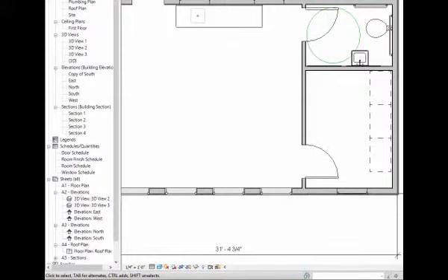As you keep on going with your dimensioning, the next most useful dimension is to put some dimensions that go from the outside faces to these interior walls that intersect, because we want to help the carpenter understand how to frame that wall. So I'll go from here to one of the faces of the interior wall, and I could go either one.